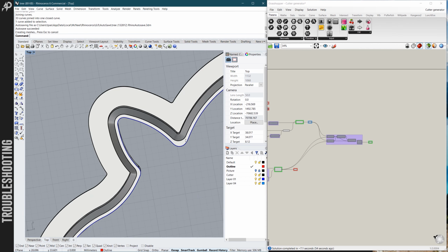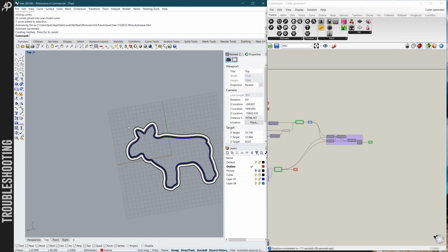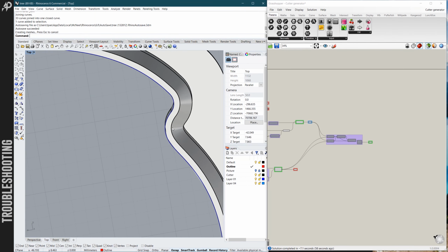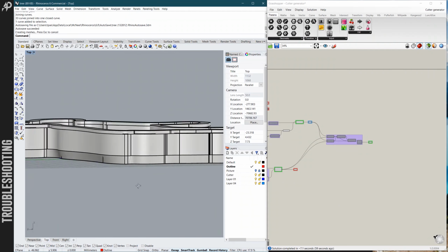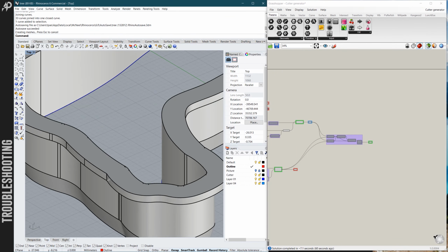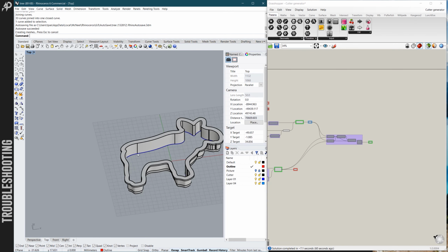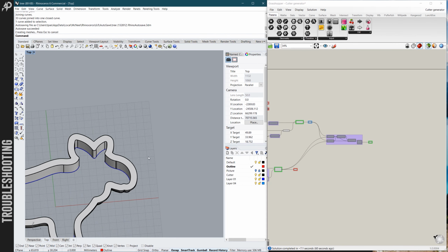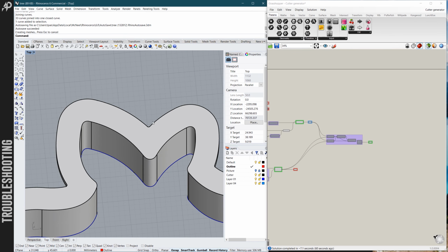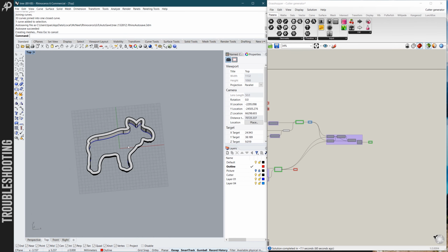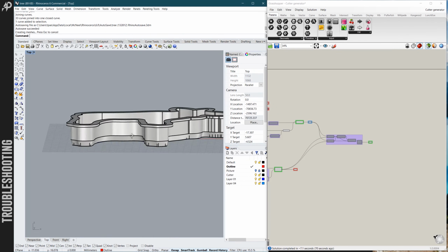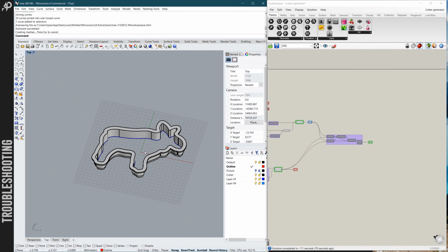But deviations like this are very small, and as I've mentioned, you don't have to really care about them. So now we've got our cutter. We can check our outer edges, whether they are continuous, and if they are continuous, we can chamfer them again and then export our file for 3D printing.